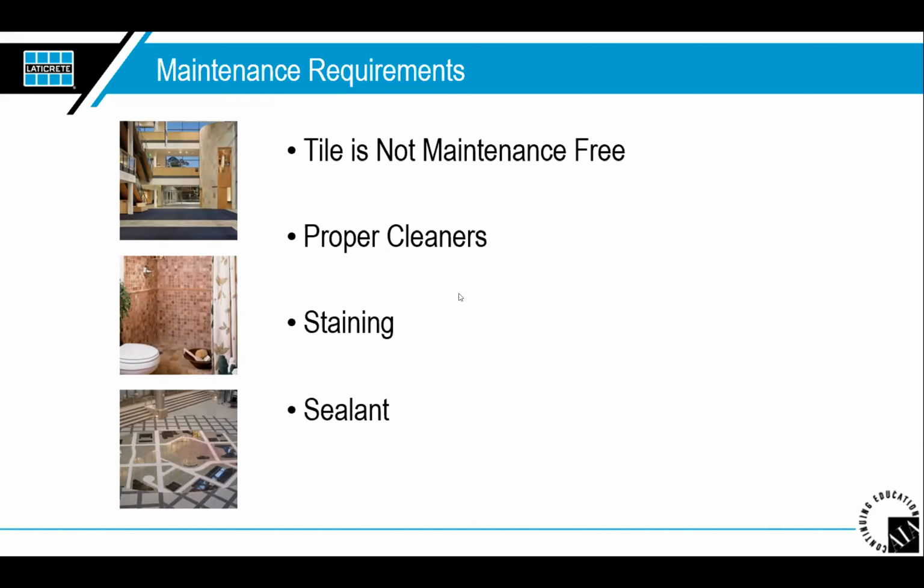So I tell people all the time, we need to have specific cleaning instructions for grout, for example, that would require a bristle brush that would go over top of the joint itself. That bristle brush agitates the surface of the grout, and then we come back over top with a dry towel and wipe down these joints. A lot of people say, well, I didn't expect all that, but in a tile installation, this is what we need to do. And if it's a wet area, it needs to be properly sloped, because that will allow the water to run down the grout joint and get into the drain itself.